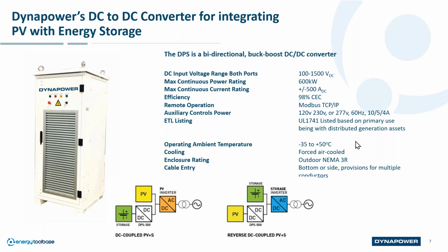The battery discharges through the DC to DC converter and supplies the PV inverter. That system is great for using any excess PV energy to charge the battery. You store it, and you can use it anytime, or you can use it to smooth out the variabilities in the solar resource. But it will not operate off grid.